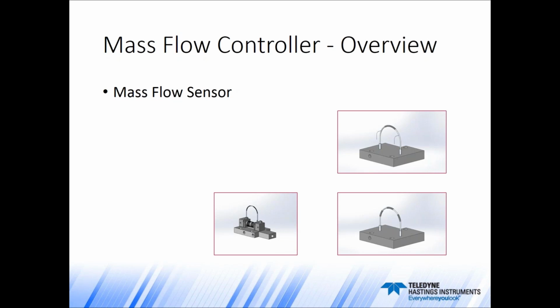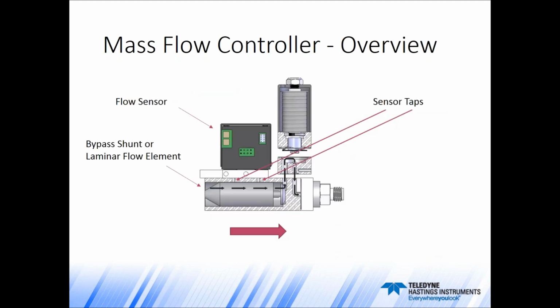But the thing to keep in mind is that the capillary tube is core to the flow measurement. It has a small diameter, so if you encounter debris, oil, corrosion, all those fun things that Antonio is going to get into later, the flow measurement and the flow control are going to be compromised. Okay, let's go back to our overview slide.